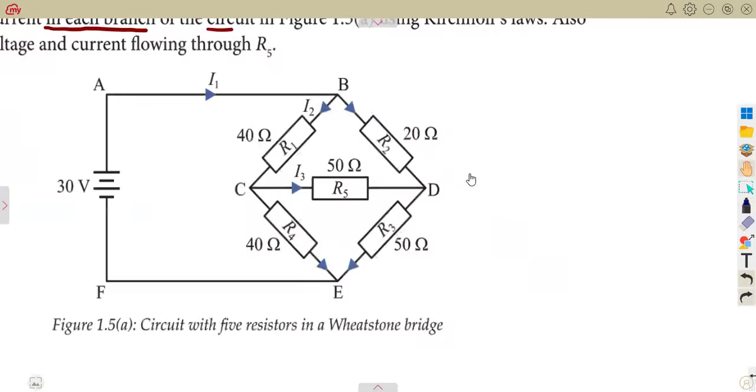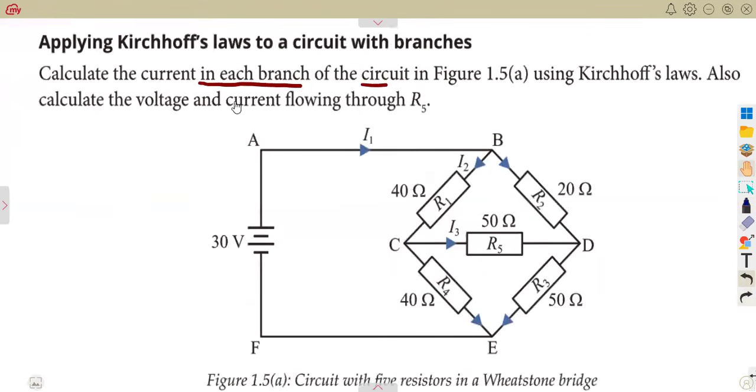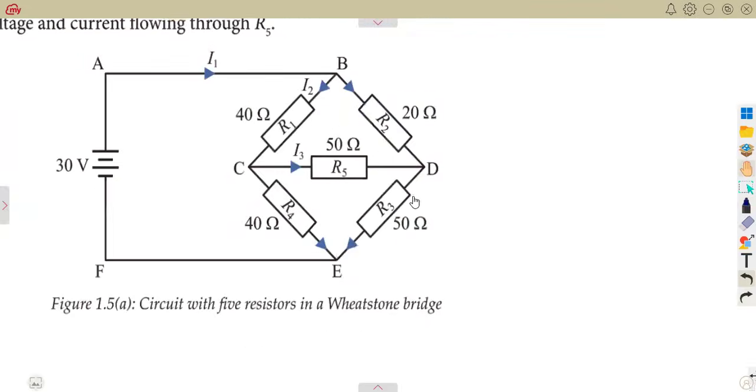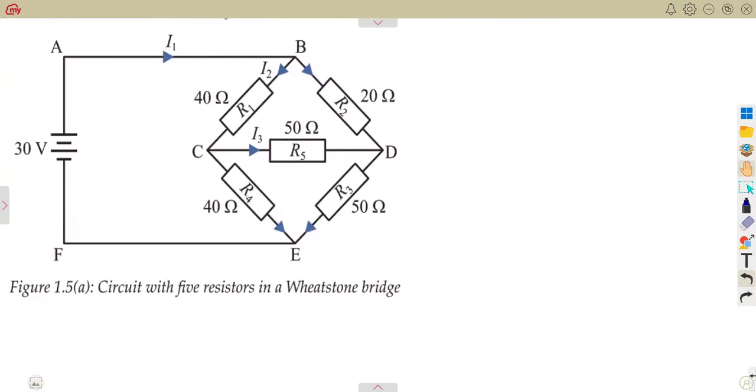Calculating first, determining, and then after that, you're going to need also to calculate the voltage. You can see that one later on. But the first thing is that we need to calculate all the currents. So the first part that you do, just determine the other currents in that case, meaning to say, just fill in the diagram, the branches. Okay, just try to fill in everything that you are given, unless they have given you that. All right, so let's apply our Kirchhoff's current law at B.